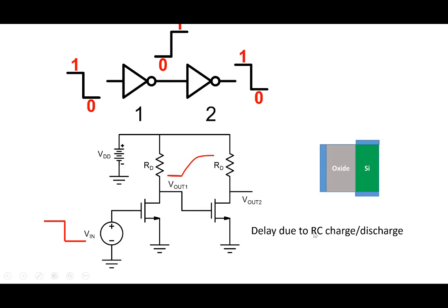So all my circuits that I have, all my complicated, let's say adders, subtractors, microprocessors, all of them have delays in them. There's a certain speed at which they work. And the fundamental reason there is a speed limit to all of this is basically because of capacitance charging and discharging. So the speed of the circuits is eventually limited by your RC circuit, a capacitor charging and discharging.